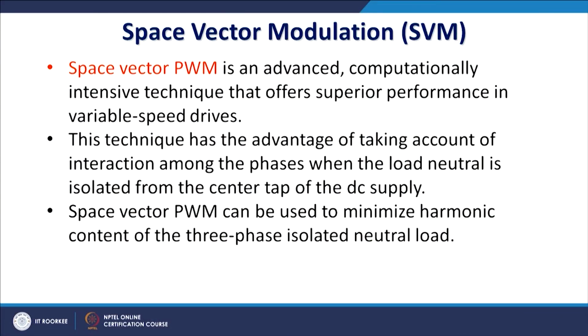And what is the advantage of it? This technique has the advantage of taking into account the interaction of the phases, and the neutral load current is isolated from the center of the DC supply. So, it will eliminate the common mode noises and signals.